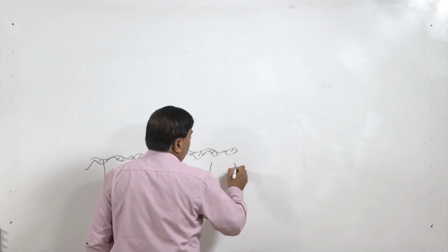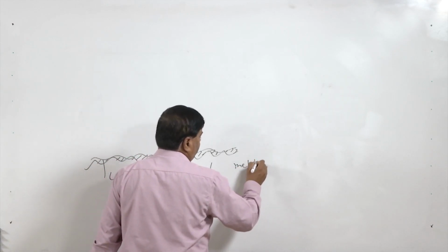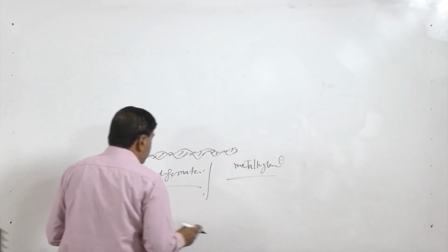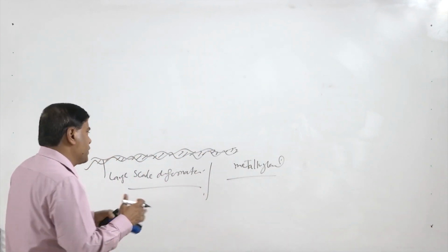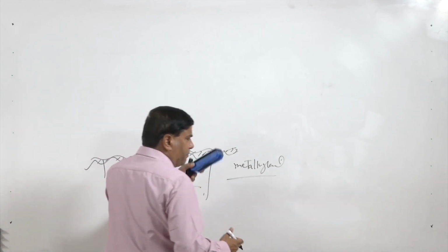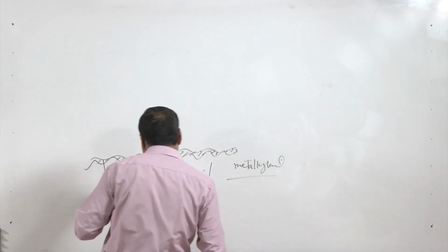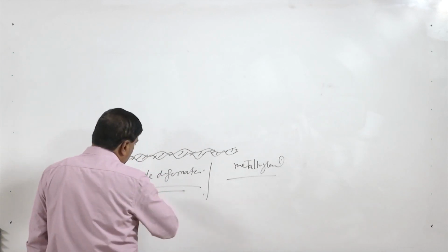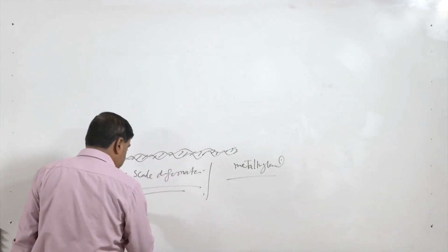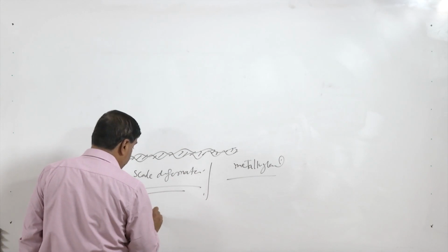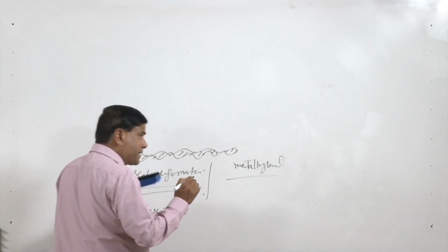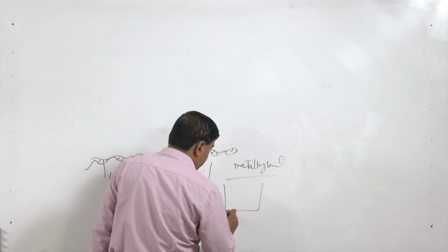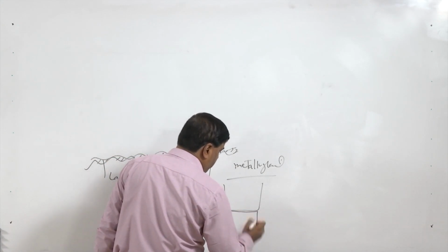Apart from that, the metallurgical continuity is obtained through the transformations, reactions, so that the grain boundary is formed across the two components being joined. This may involve a lot of plastic deformation. Another is the diffusion way, where the deformation is extremely negligible. The two systems are brought in direct metal to metal contact under pressure.